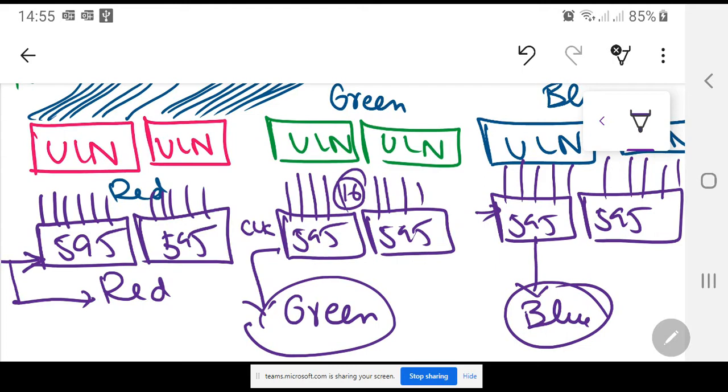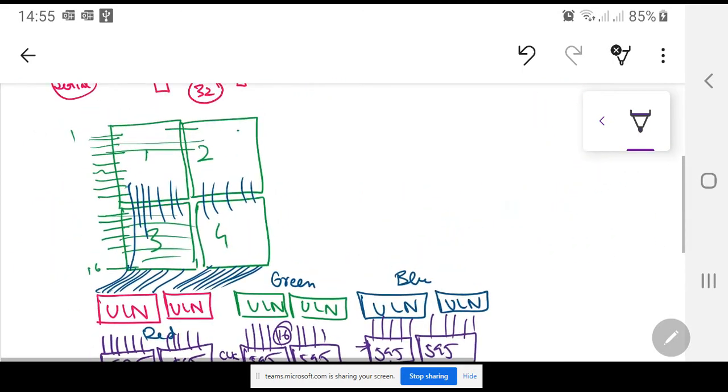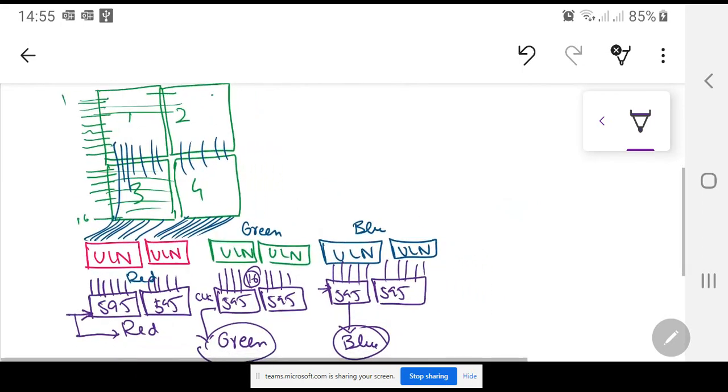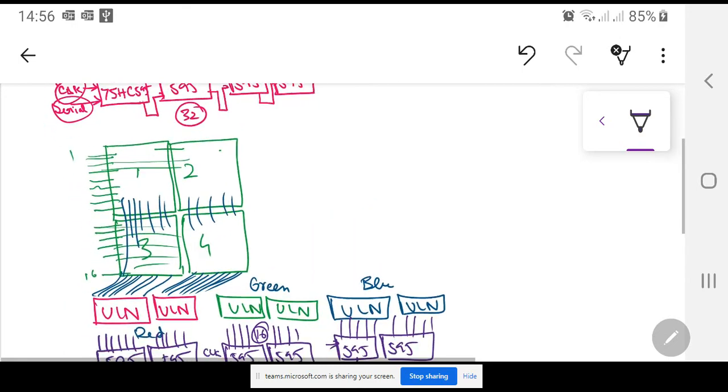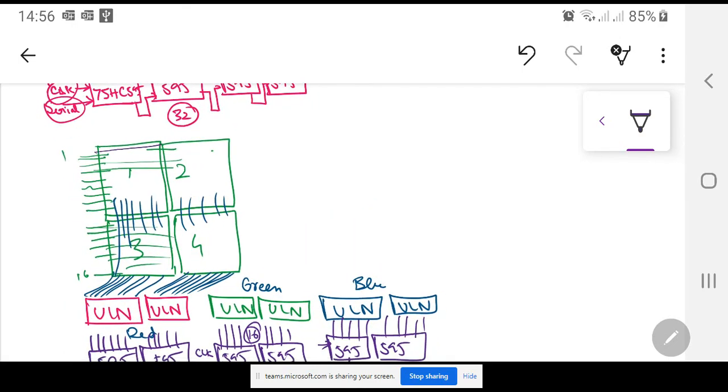So at the end of the day, the point is that you are making the interface with the controller easy. But yes, when you see this whole PCB, it will be very, very large. Now, as far as the size is concerned, the ideal size is this. Remember, for all projects, all of the PCBs should be equal to the size of their dot matrices arranged. When you're talking about RGB, you know the dimensions of your RGB here. So you know 2 of them, 3 of them and 4 of them. Better if all the circuitry remains inside this area, that is the area in front of the dot matrix.